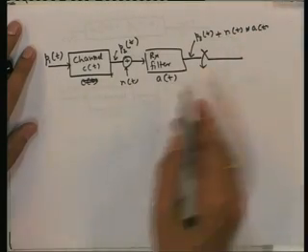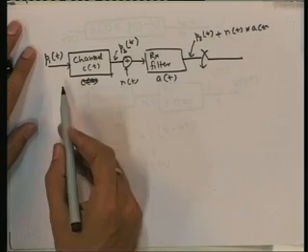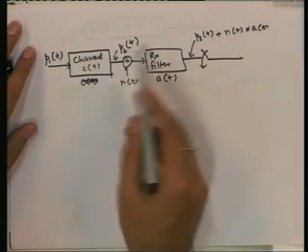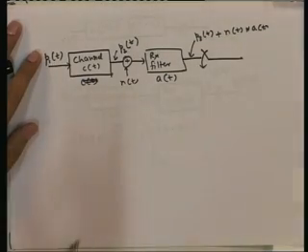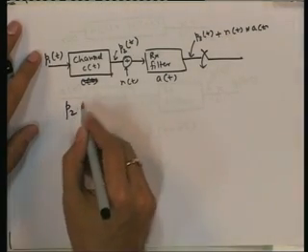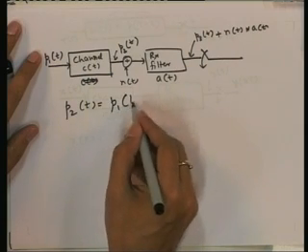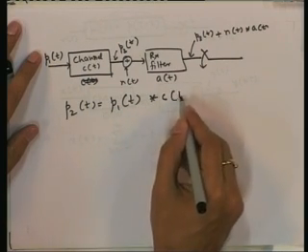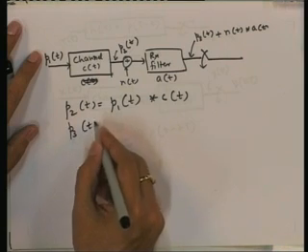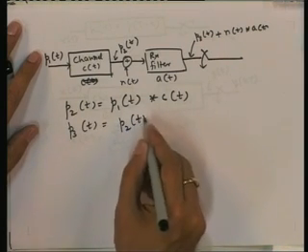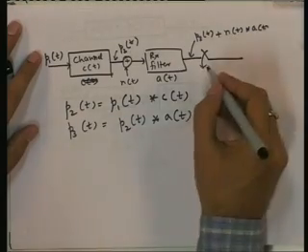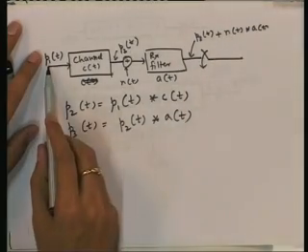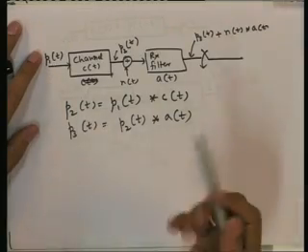So remember these things, this is the output only when you give this as input. Only one pulse you give as input. So p2(t) is nothing but p1(t) convolved with c(t), and p3(t) is nothing but p2(t) convolved with a(t). Then we are sampling every T seconds. So if we transmit simply p1(t), we will sample at capital T and see what we get.